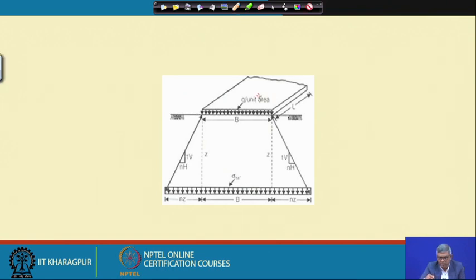In this figure you can see a foundation shown here, maybe extended this side, and this is the width. Approximately, we can assume that the vertical pressure is dispersed at some particular angle. So if I apply load here, the load will not go vertically, it will be slowly dispersed over depth like this.